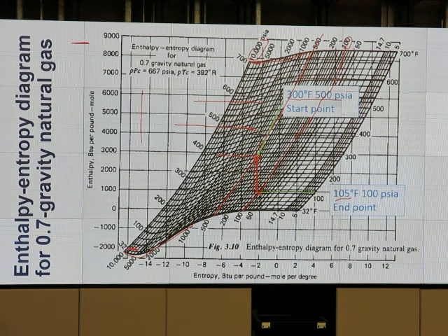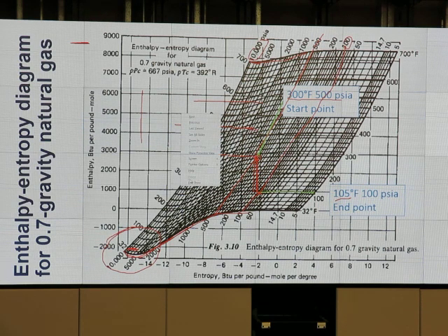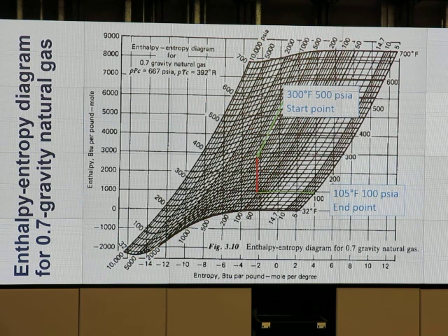The temperature goes up a little bit because this constant temperature line is like an S curve. So this part of the curve, at very high pressure, when it bends like the S shape, okay, a constant temperature line, whenever it is kind of S shape, when we decrease the pressure, it can get a little hotter. This place will be more obvious, but that's a rare case. Most of the time, when pressure drops, it's getting colder. So that's why we call it the JT cooling effect, right?